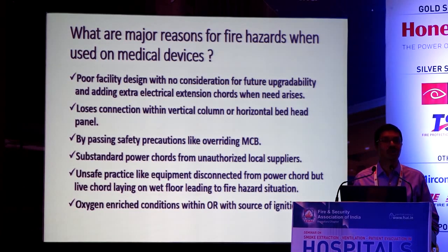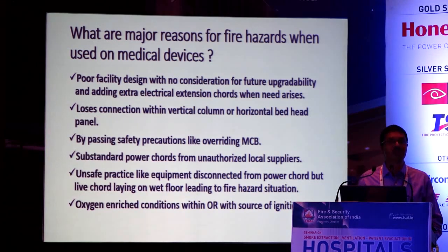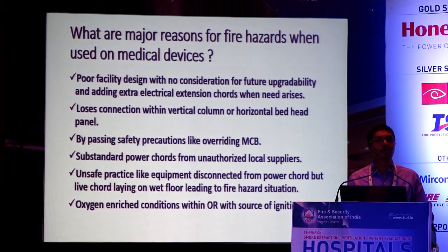Then there are substandard power cords from unauthorized local suppliers. This is an incident I have come across in my experience, wherein one of our purchase team said, okay, we cannot take the power cord from the OEM, very costly, we go for the local. And it was not even known to the clinical engineering. Later on, in one of the ICUs, there was a spark. When the root cause analysis was done, we realized that the cord was cheap, very brittle, and it does not even sustain the power which is passing through it. So we should not bypass.